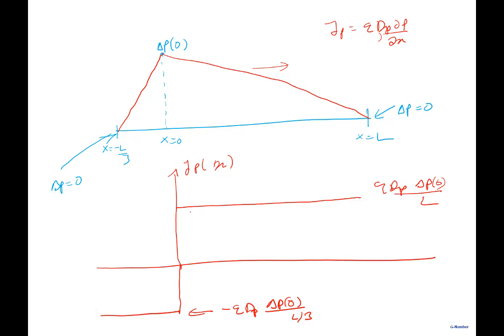Okay, so far fine. This is okay. Total current through the device should be constant, right? J should be constant. J equal to Jn plus Jp equal to constant, correct? Whatever that current is in steady state, the same current will flow everywhere. So there must be Jn somewhere. This can't be the situation. Jn is also flowing. So what happens to Jn then? How do I calculate Jn? So this is Jp. Then how do I calculate Jn?